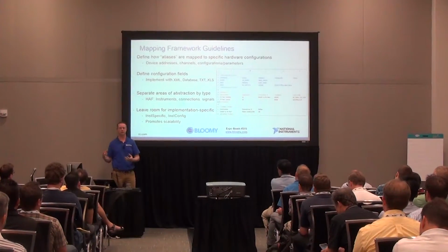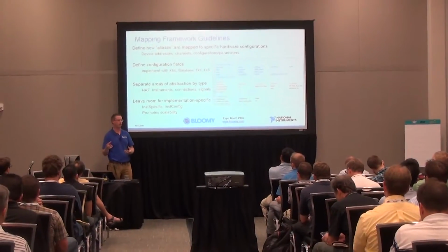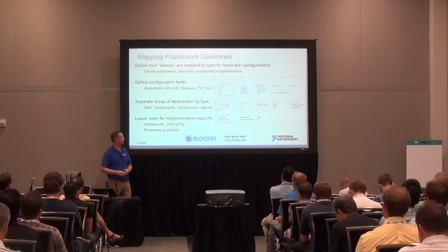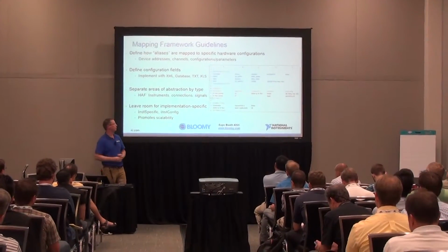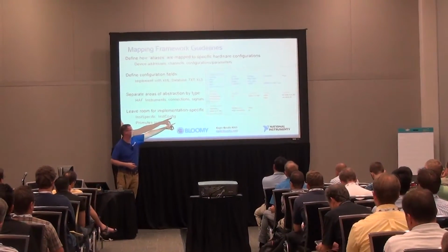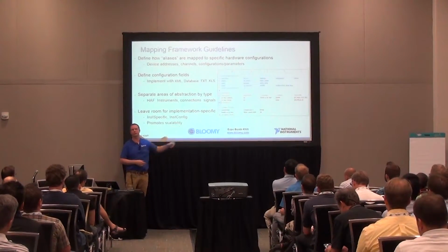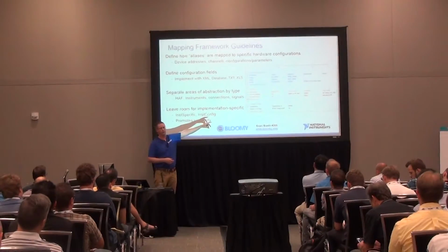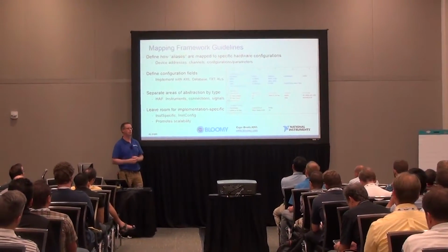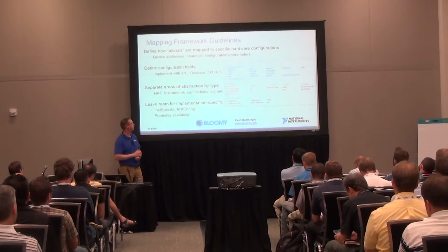Same thing with those connections. Some signals may require some connections associated with them if you have a switched DMM. Other signals don't. If you have 24 analog inputs, you may not need to multiplex those. And so doing that same 5-volt rail measurement with our DMM, you'll notice I define a connection, which is DMM to 5-volt rail. That connection is an alias which defines some actual physical connections in the system. The analog input one doesn't define that connection because it doesn't need to be switched. And so you can use these at different levels of abstraction to make it easier to make changes and make it easier to configure your system.